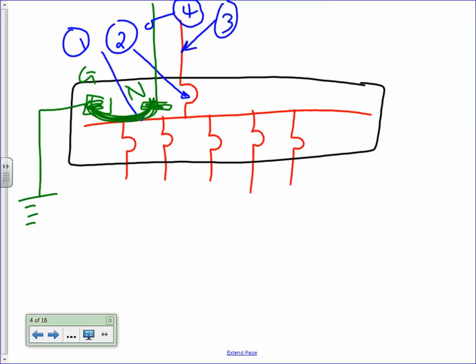Again, I have a lot of sheets, guys, about grounding and bonding, so I don't want to make it grounding and bonding for the time being. I just want you to understand the 4 things that we size. Can I have a thumbs up, chat? We fully understand how to size the following. Number 1, the panel. Number 2, the overcurrent protection device. Number 3, the phases, when we go to 3-phase. And number 4 is the neutral with the rating.